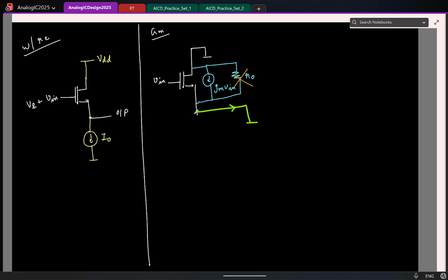Right. So I'm interested to measure the short circuit current ISC. So what is the short circuit current? Plus, minus? I mean, I have the current flowing down, the same current is going to flow through the short circuit. So it is the same sign. So which means what is my short circuit GM? Capital GM. It is the operating point transconductance GM of this transistor.